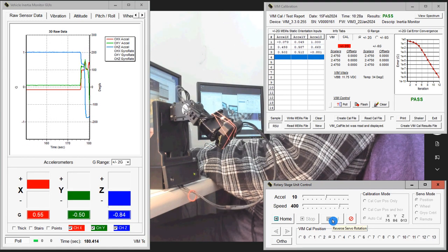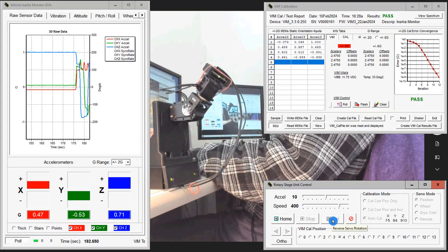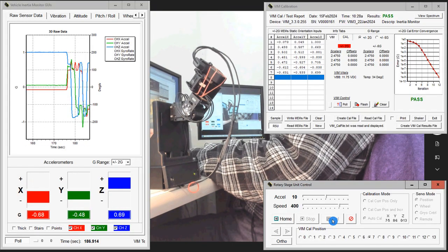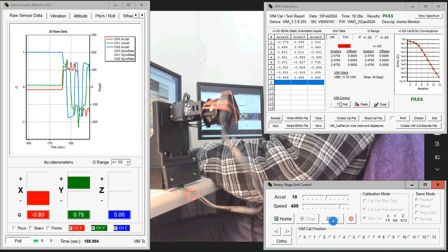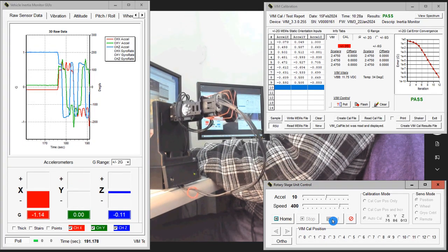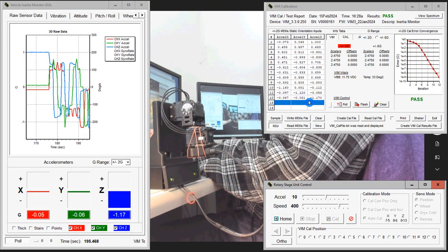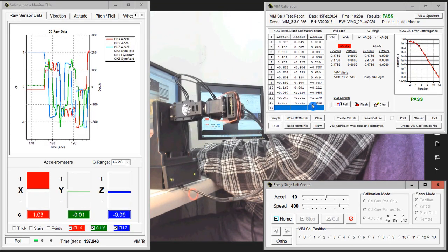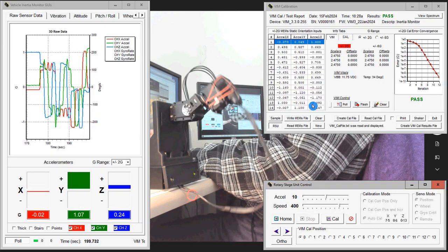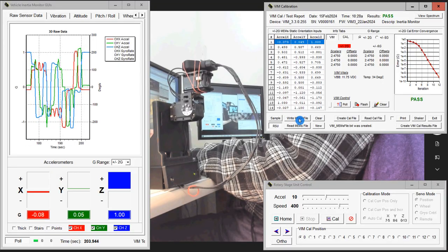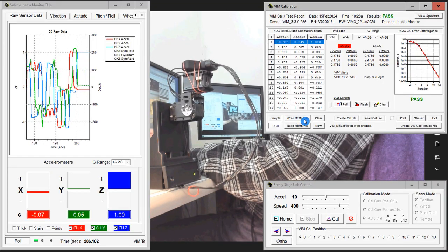The servos step through casted orientations of each location of the inertia monitor device, and upon completion, the raw MEMS information of X, Y, and Z that is measured from the non-calibrated accelerometer is saved. This raw information is saved to a MEMS file.